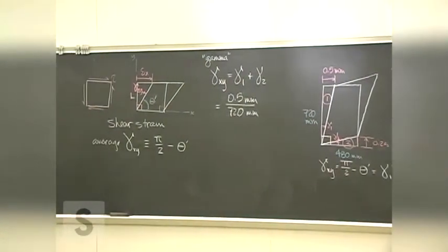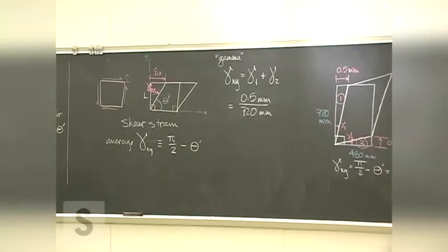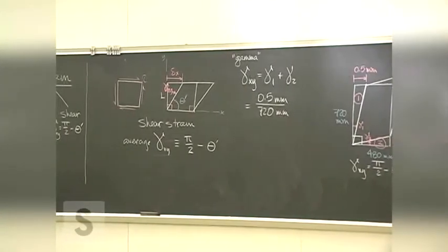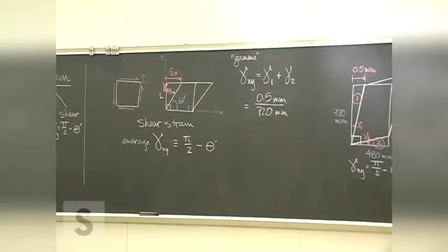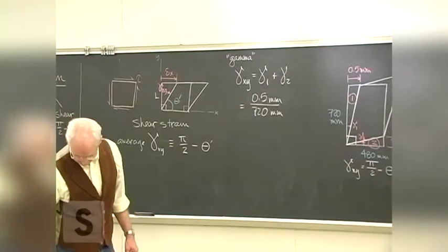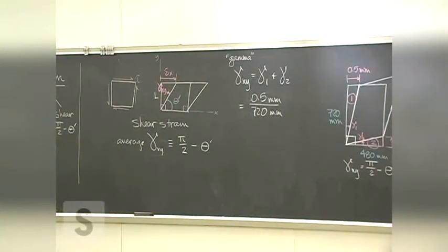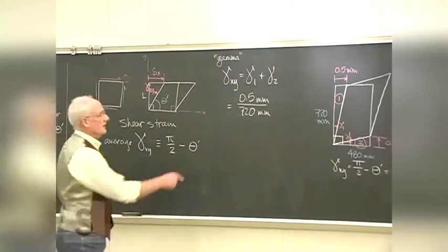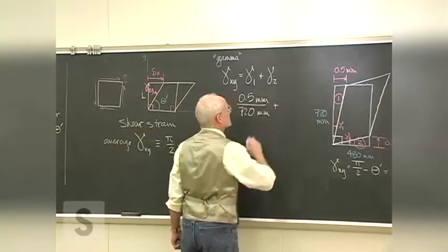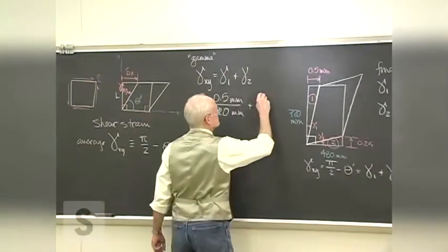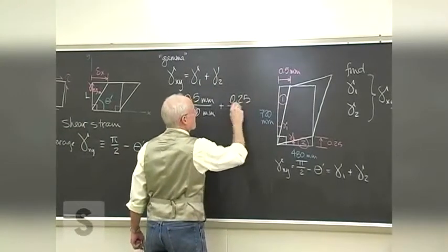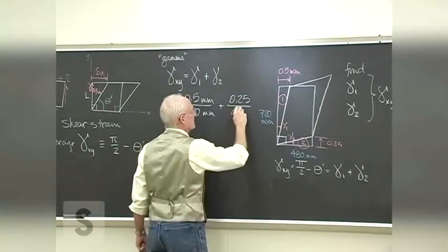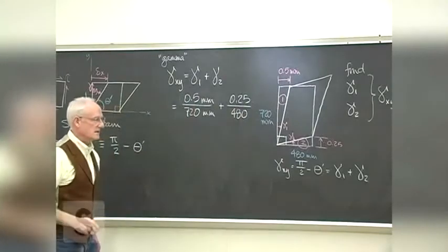These are very, very small angles, so we don't need to take the tangent of them, because the tangent of a very, very small number is the same as the number itself. That's also why you didn't use that method when you showed us the differential means of showing strain. You can, if you see it better that way, take the tangents. And then this is over the original piece itself.